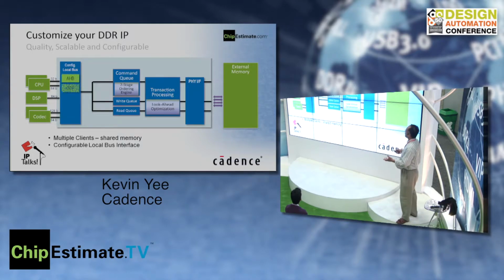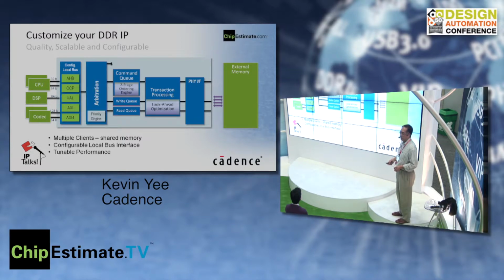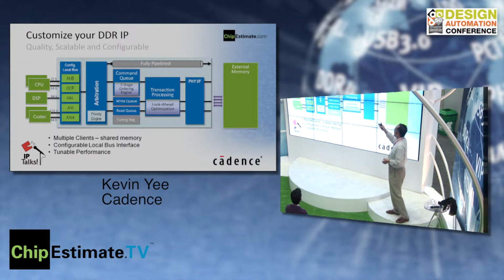To give you more configuration, we allow you to choose what your local bus is going to look like, whether it's AHB or OCP or AXI. Next thing is, in terms of tunable performance, whether you want fully pipeline, tuning registers, we have an arbitration engine and a priority engine, so if you have multiple clients, you can manage your performance through the controller.